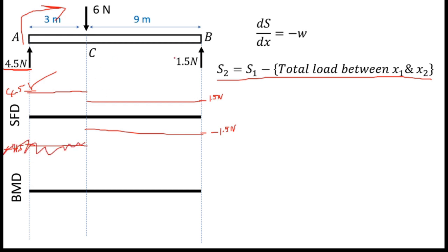Likewise, for this force, if we take moment of this force about AOC, it goes like this. So it is counterclockwise direction. Our sign convention says clockwise positive, that means counterclockwise negative. So moment due to this force is counterclockwise, that means it is negative. So our value is this value, so I can eliminate this value.